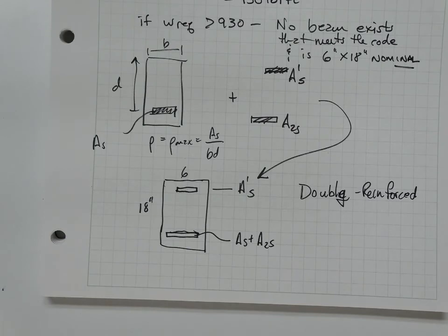The way we're going to resist shear forces is we're going to build our beams so that bars will sit in this orientation in the beam. And when the shear comes to tear it apart, it's got to shear the concrete, which has shear strength. And it has to shear through this steel.